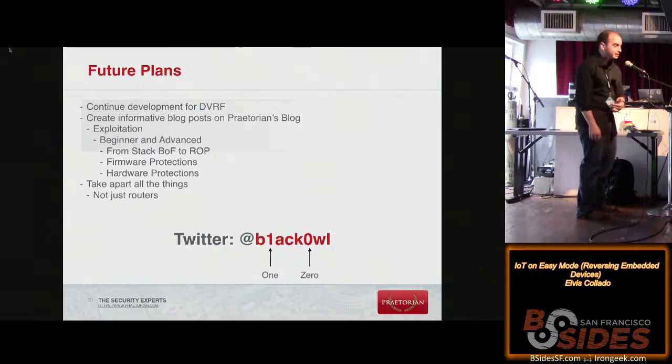So this is, again, supposed to be an ongoing thing, for people to learn about exploitation, hardware stuff, the complete hardware and software stack. And I'll also go on to future stuff, because I believe the FCC just came out a few days ago saying they want to start hardening firmware. They want to start locking down these things and make it more secure. And also there's hardware protections. Like the silliest ones I've seen is where the JTAG traceouts, when you look at the pins, are just cut. So you can just put some continuity there, boom, you got JTAG. Or they just completely disable it altogether, but that's another story. And once I dig into that a little bit further, I'll be posting about that so you guys can be more aware and also be having more fun with your hardware.